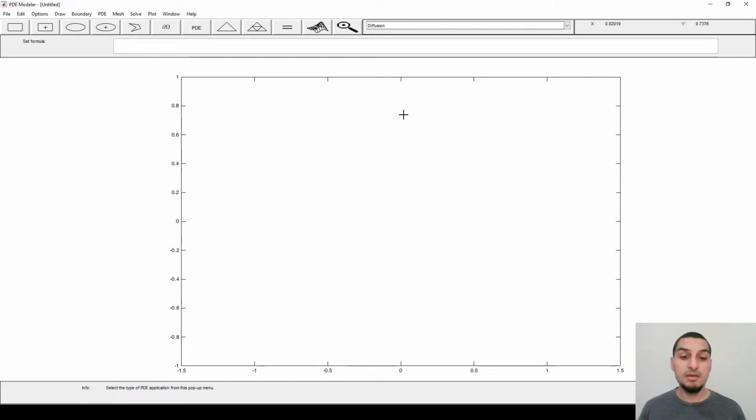So the adjustment of these units is your task as a user. You have to make sure that you define your inputs well, and that the units of all the inputs are homogeneous. If you're using centimeter as the unit of length, then everything is in centimeter. For time in second, then everything is in second.